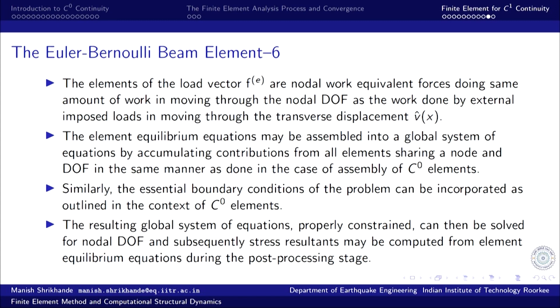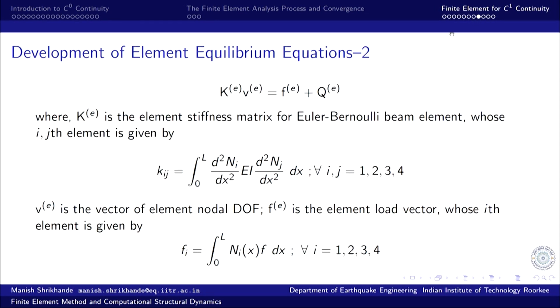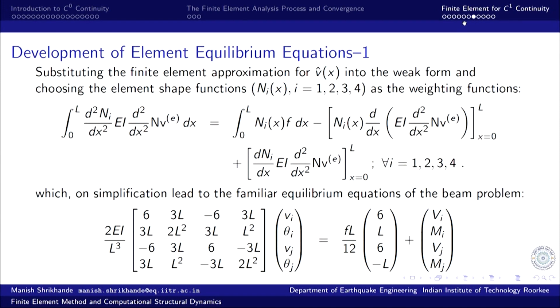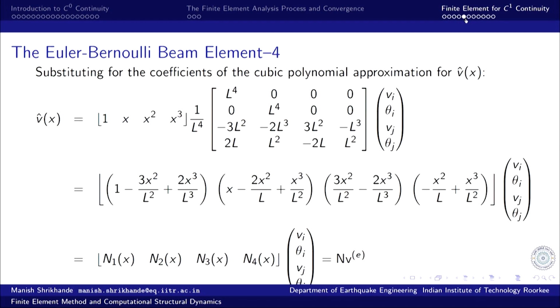the post processing stage. Because once we have this complete displacement, then we can compute the moment and shear force by the appropriate derivative. So, for bending moment, we get this displacement function as a function of x in terms of interpolation of these primary variables, which we will get from the solution of global system of equations.